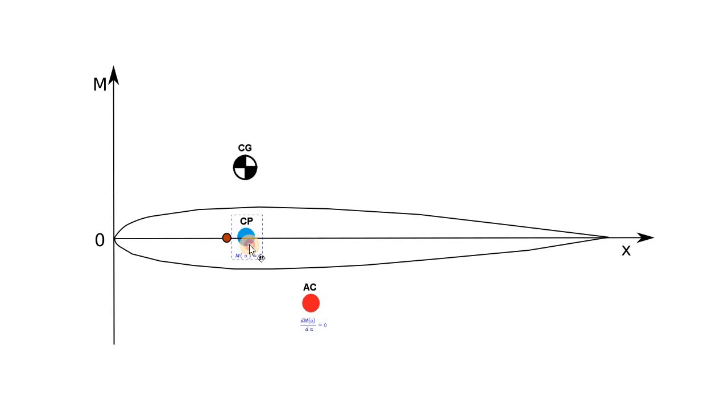The position is going to be defined by the angle of attack. The same is true for the aerodynamic center. Well, it stays constant for a small change of alpha, but if the change in angle of attack is significant, we're going to have a different position for this point as well.